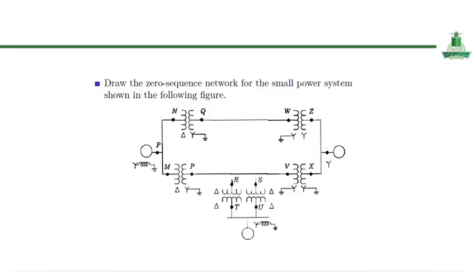The key challenge here is to identify how zero sequence currents can propagate through each section of the system, as in the previous network: grounded star-star connections provide a return path for zero sequence currents, while delta windings either block these currents from passing between the buses or allow them to circulate only locally within the transformer.